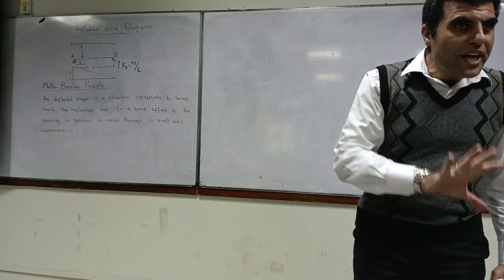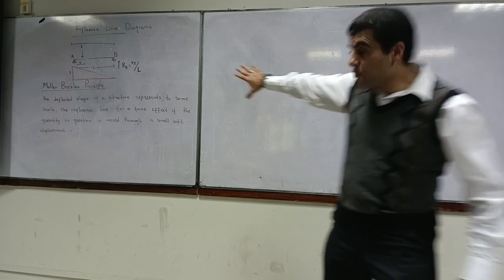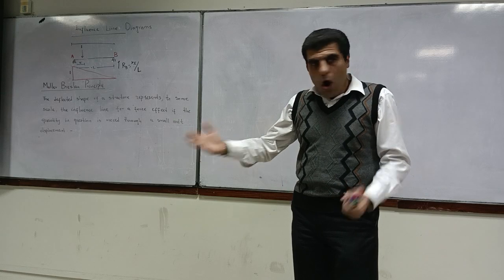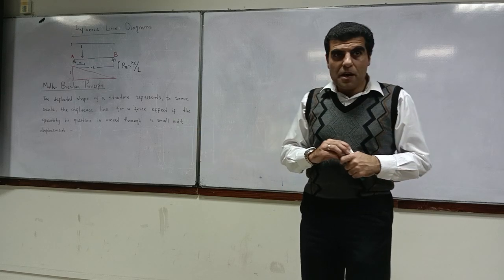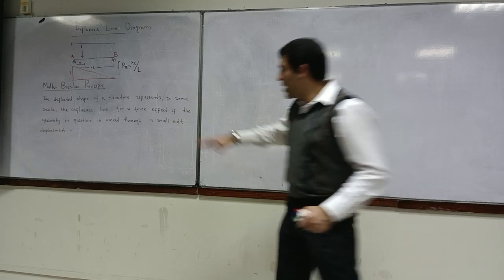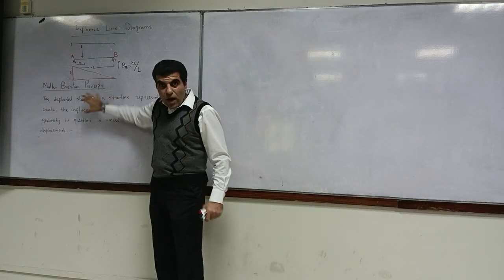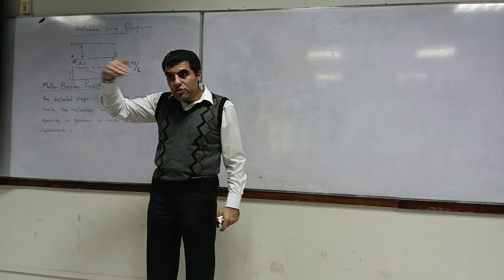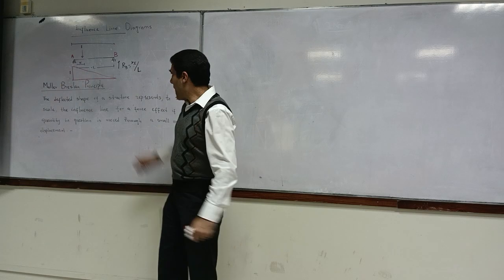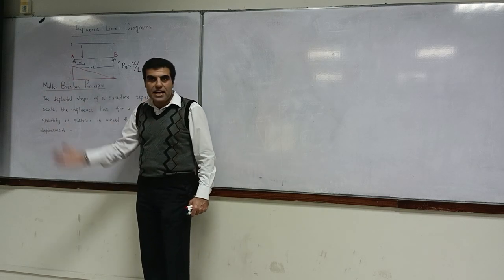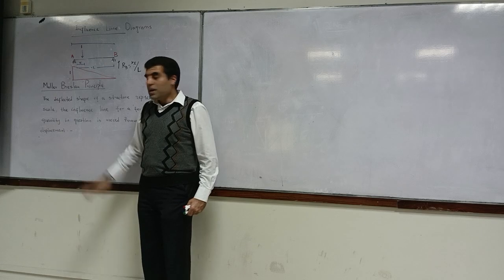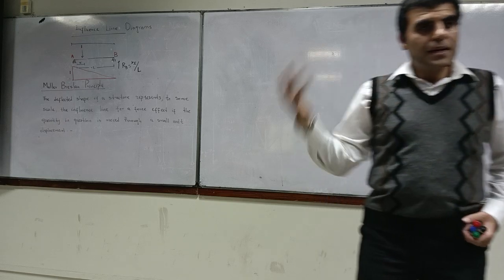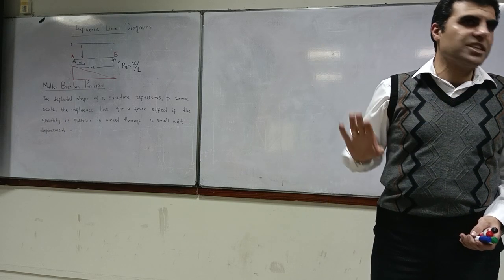Either you can use the first principle which we did over here, using equilibrium to find out your influence line, or you can use the Muller-Breslau principle. This principle makes our life very easy because it will straight away give you the magnitudes and everything, rather than going through the rigmarole of using equilibrium to find the reaction. So this doesn't have any effect on the applied load. It is just about the deflected profile.